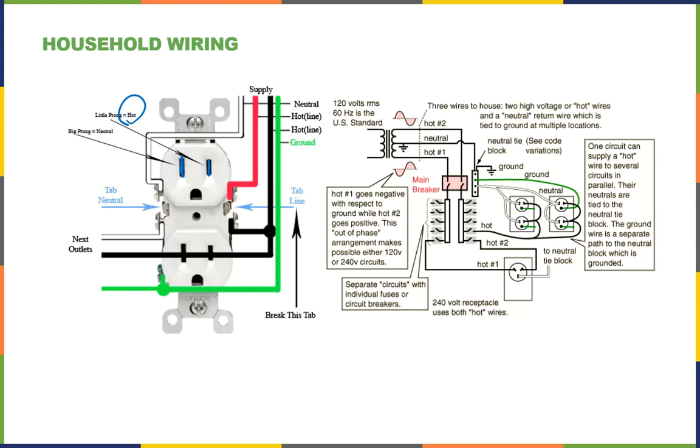But you could still, if you have a fault, like let's say your refrigerator has some wire that falls against the chassis, you can still get shocked by that. So we're going to go one step further for safety. We're going to put a 3rd wire. So houses today are always wired with 3 wires. The first 2, the hot wire and the neutral wire. And then the last one, the ground.